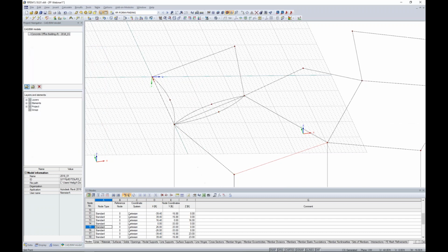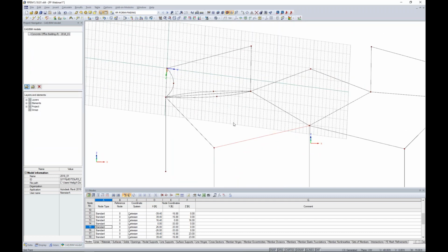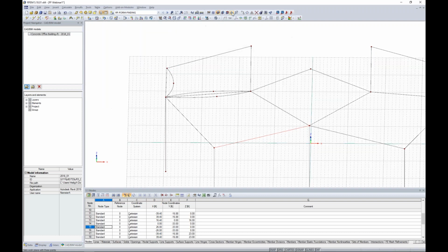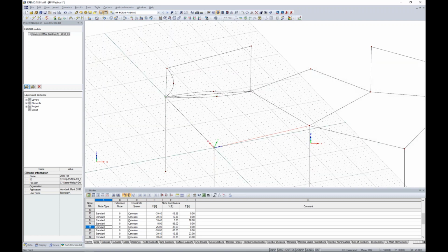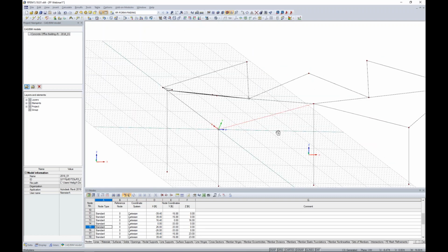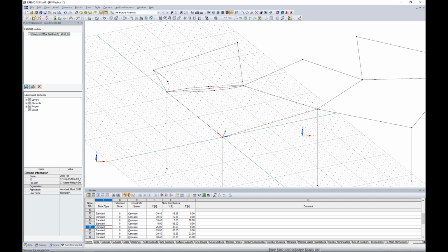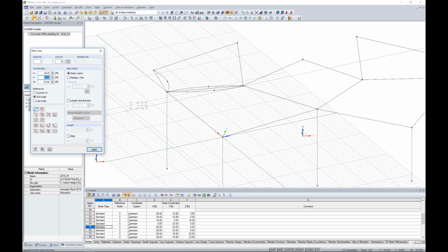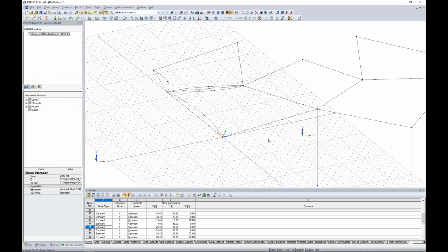Again, completely arbitrary. We need to move up to the second cell and we need to change our user-defined drawing grid. So I click first to reset the drawing grid, click it again to define my new point, and I can click on 3 points here. And now you'll notice that I have a new drawing grid at a specified angle. So we go to draw a new angle here with the given arc, and I can simply snap to these points, again, any arbitrary points.